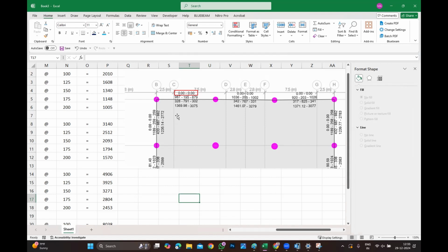What is the difference between vertical shear and torsional shear? When you have side face reinforcement, regardless of the minimum rebar in the code, when it is required, regardless of torsion, you need the side face reinforcement. That is fine. That is code.